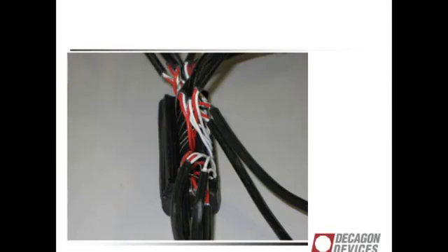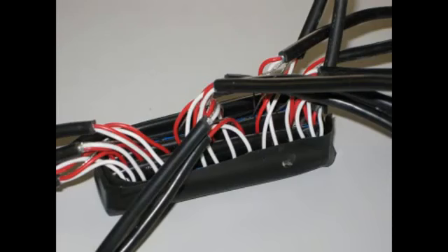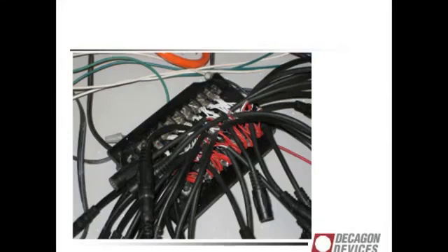Here's another homemade bus. Basically, anything that works, you can do for this. But I don't know if I want to put electrical tape out in a sensor network in the field. Changing temperatures do some pretty crazy things to tape, and if this bus falls apart on you, you're going to lose all of your data for that time period. So, if you're making a homemade bus, you want to make it to last.